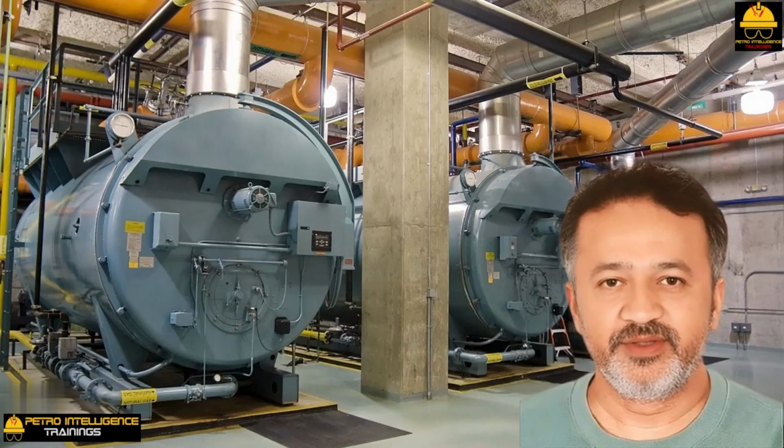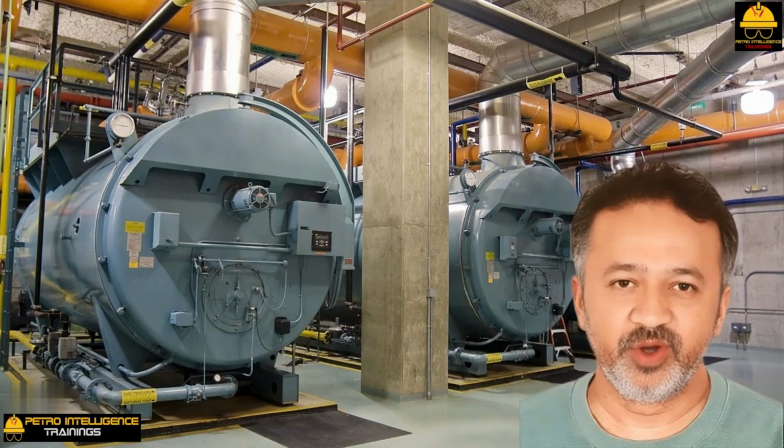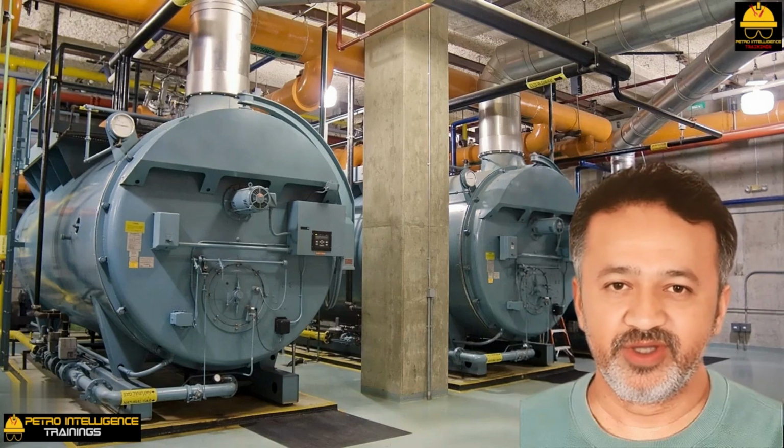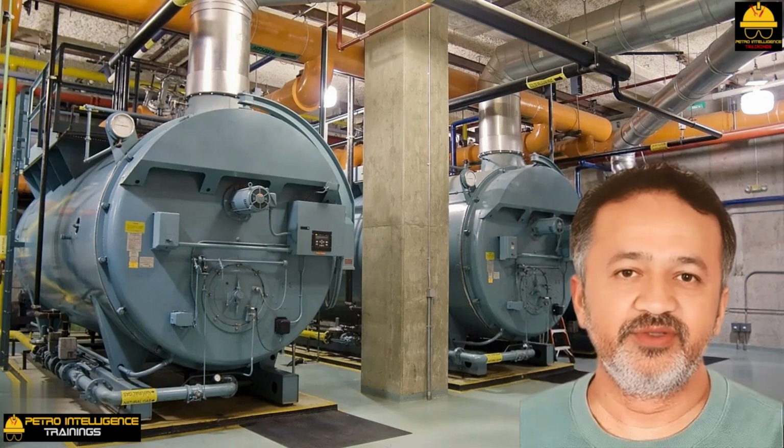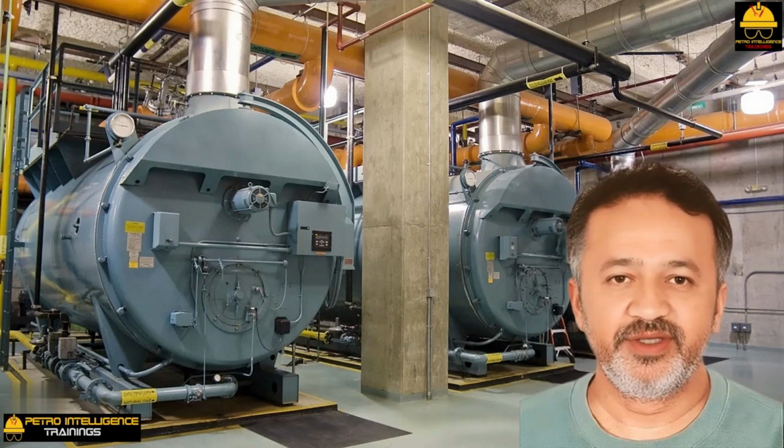Boiler feedwater preheat. The optimum feed temperature to a deaerator is the boiling point of water at the deaerator pressure, typically 230 degrees Fahrenheit to 240 degrees Fahrenheit. However, in many plants, BFW to the deaerator is heated to 160 degrees Fahrenheit to 180 degrees Fahrenheit by heat exchange with process pump-around or product streams.